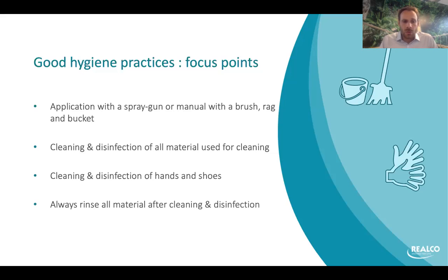Also, as I said, always rinse all material after cleaning and disinfection, because you are using chemicals, and the chemicals have not been designed to be in contact with the product you are producing. I know that with some molecules, some people like to leave the product in contact with the surfaces, but it's also very important to rinse them to be sure that there are no remaining chemical residues on the surfaces before the production.